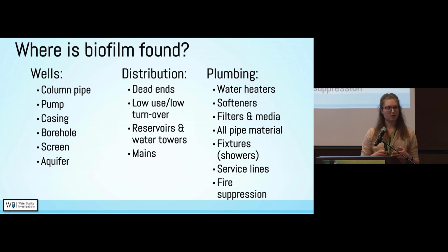We found biofilm in all pipe materials, whether it's PVC, PEX, copper, galvanized. It just basically changes the structure of the biofilm because it's searching for something different. We see a lot of biofilm growth in fixtures, specifically showers. One such area that we've seen a lot of issues with, for instance in a hotel, is ADA accessible rooms.